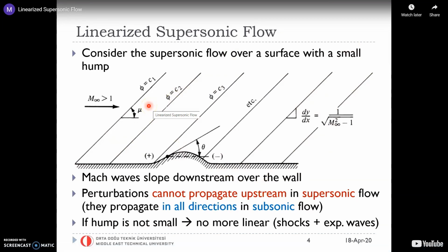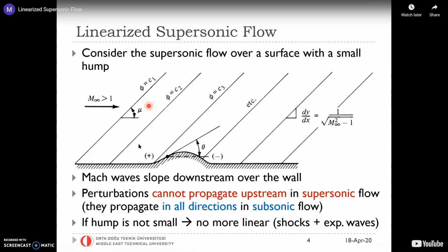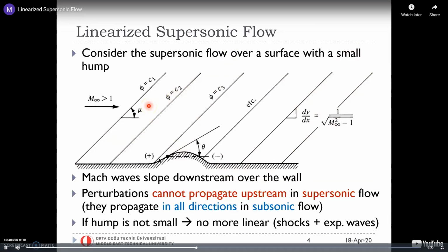But since we are in the supersonic regime, this 1 minus M infinity squared becomes a negative number in that differential equation. When it becomes a negative number, mathematically, it becomes what we categorize as a hyperbolic partial differential equation, okay? And physically, I guess they represent exactly this kind of characteristic.